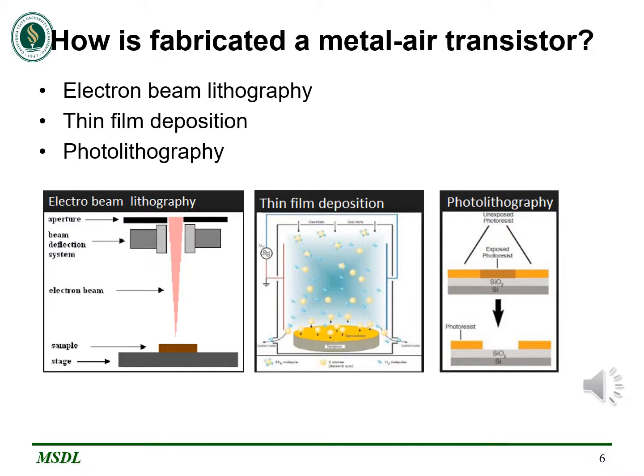First, EL3 copolymer was spin coated and soft baked at 180 degrees Celsius for 5 minutes. Then PMMA A2 was spin coated followed by identical soft baking.